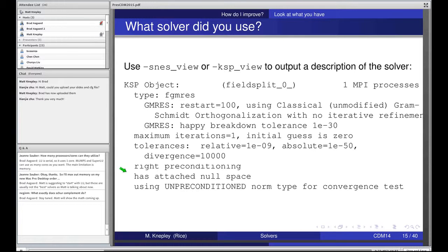Certain kinds of solvers need to understand the analytic structure of your operator. So let me give you an example of this. The elastic operator, the pure elastic operator, has, let's say in 2D, a null space of size 3. Why?